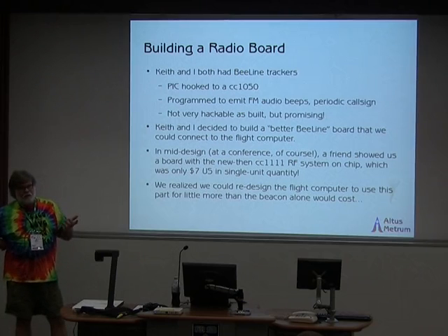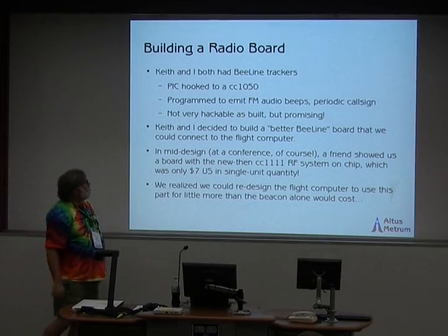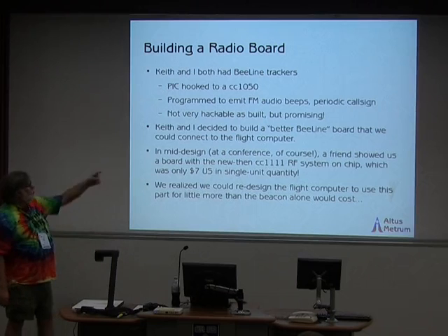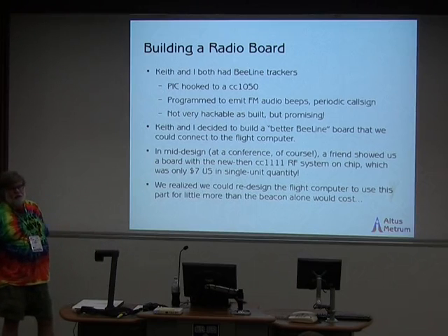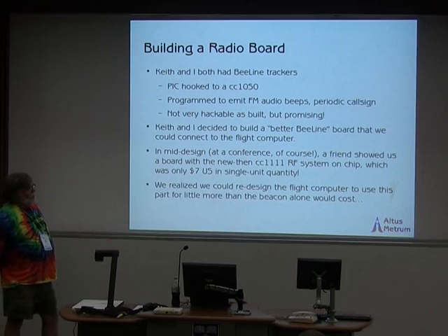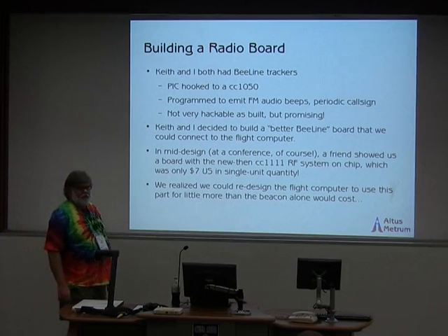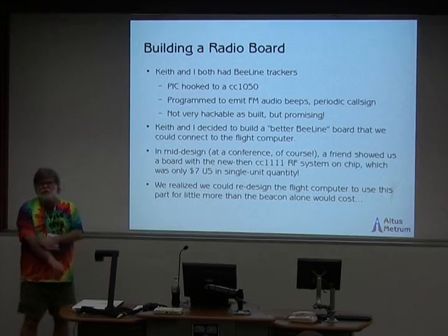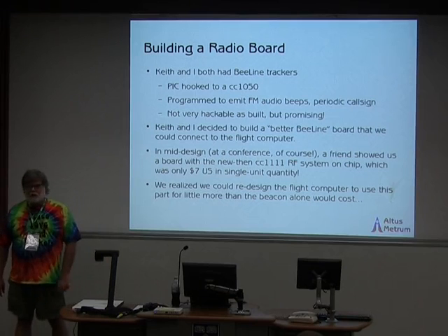So if you had an FM, a 2 meter, 70 centimeter, in this case 70 centimeter HT with a little Yagi, you could use this for radio direction finding. It would occasionally put out the call sign to meet amateur radio regulatory requirements. But it wasn't very hackable as it was built. And what I mean by that is there were extra pins on the PIC that you could have used to provide some serial data in from the flight computer, but they weren't brought out to anything that you could easily attach to.